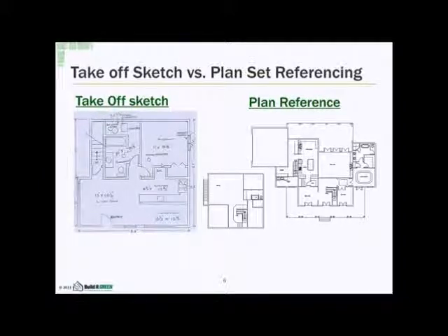But with your multifamily buildings, it will take you a very long time to draw the building, so you can most likely leave this information out. You can probably keep information about the stairs and the windows, but interior walls and the toilets and the sinks and the stove countertops, where those are located, and each room dimension is not necessary. What the takeoff sketch really needs to have is the exterior wall dimensions and window locations and dimensions.